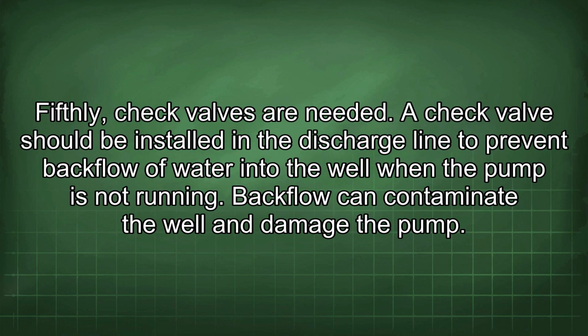Fifthly, check valves are needed. A check valve should be installed in the discharge line to prevent backflow of water into the well when the pump is not running. Backflow can contaminate the well and damage the pump.